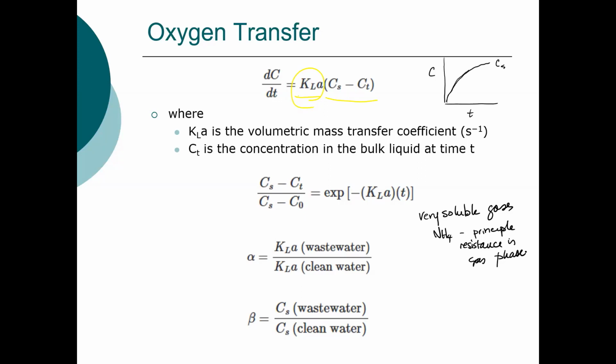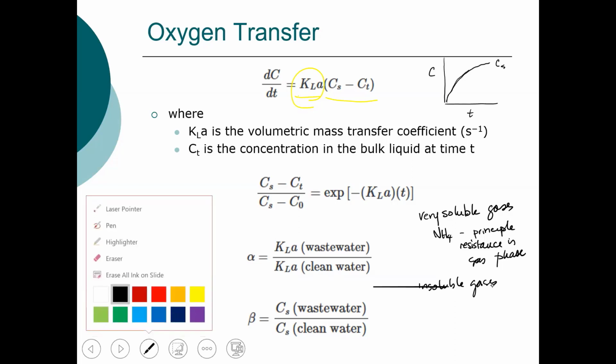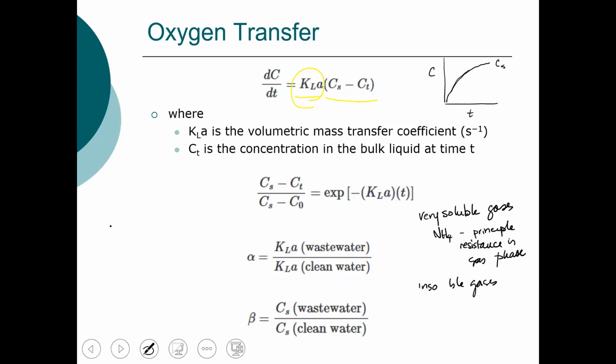On the other hand, for relatively insoluble gases, and oxygen is a relatively insoluble gas, the resistance is predominantly in the liquid film. So mixing the liquid in order to reduce the liquid film thickness actually is beneficial. So understanding the influence of solubility plays a significant role.